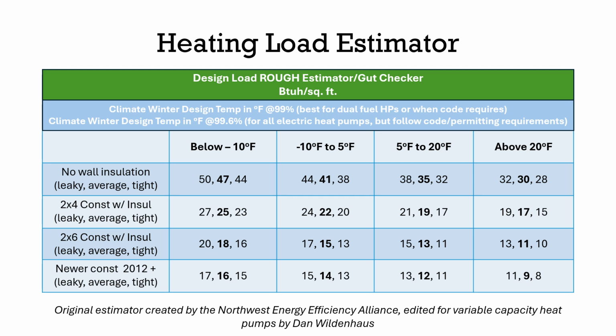This allows me to do a lot of different things, right? To take into account where the house is, to take into account how insulated and air sealed it is, right? All of these, the size of the house, because we're doing BTU per hour per square foot and multiplying by the square feet. So this is an enhanced rule of thumb tool that gives us the ability to fine tune a lot more than a standard. Again, we're not using this to replace a load calculation, but to check to see if the existing equipment is within the realm of possibility, this might be a good tool, or if my only other choice is to size off of the existing equipment, or if I'm using ductless heat pumps only. Those are the real good use cases for this.